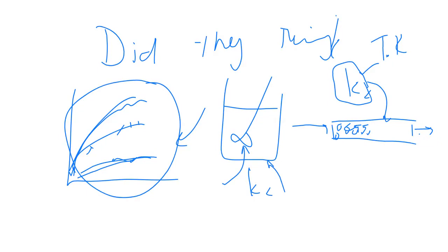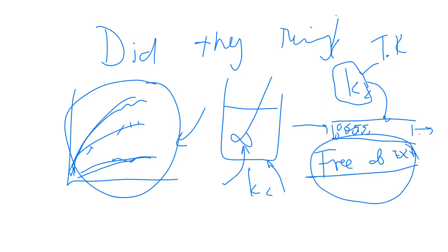So you must make sure that the person who published the data, or if you are publishing the data, proves to you that the rate data that he publishes is free of external diffusion effects. So this is one of the main things, how you will apply it in your design. Not for this, but for the semester test and the TATS, I test you on analyzing data where it is in fact constrained, and to realize when the data is constrained by external diffusion effects. So you must make sure that all the experiments are free of that.